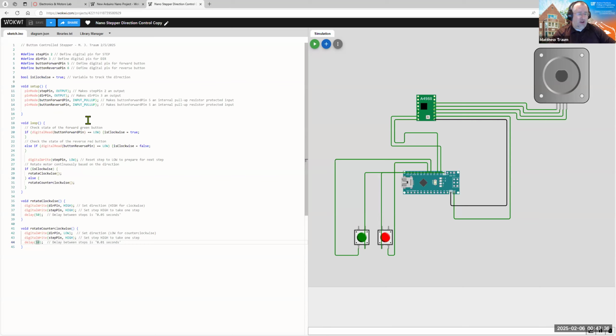And remember in class, we talked about noise being kind of the killer of digital devices. So notice that I'm declaring these two pins as input pull-up pins. Remember, when you use the pull-up feature, there's an internal pull-up resistor in the Arduino board, and that will enable the pull-up resistor, which is basically a way of mitigating noise. So I'm intentionally declaring these as inputs attached to a pull-up resistor.